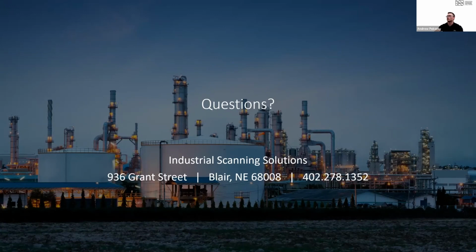Talking about getting control in there and transferring and moving around, and depending on whether or not we're using the P40 versus the RTC360, we can get in and get out and then come back. In the registration of that, if you're talking about registering less than 150 scans, we can usually get that imported overnight, and then get it all registered over the next day, and then maybe work on quality control checks and whatnot the next day. So the turnaround's pretty quick, I'd say less than a week on all that, and then we can get into modeling, and that gets really detailed depending on what level of detail you're trying to capture. So good question.